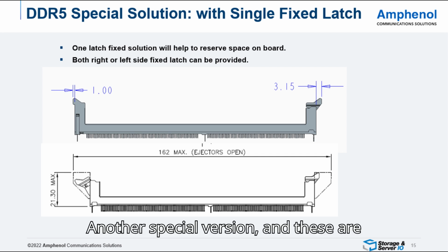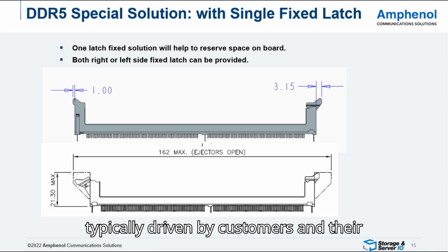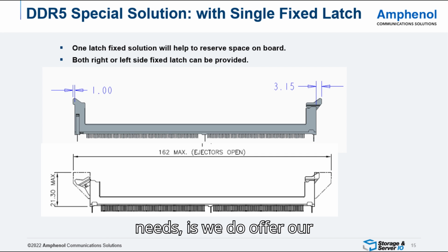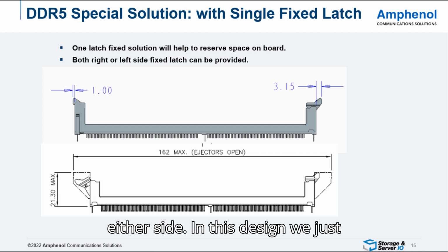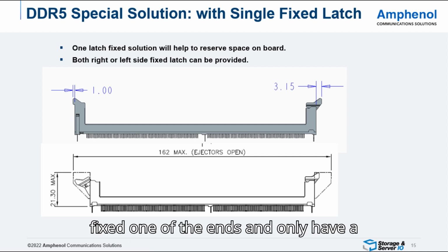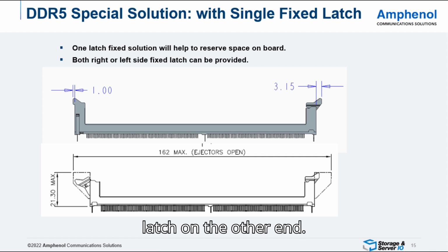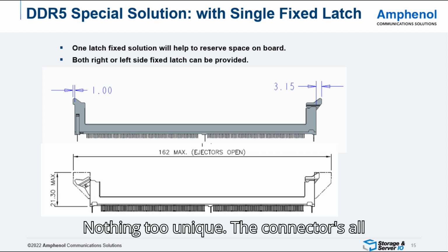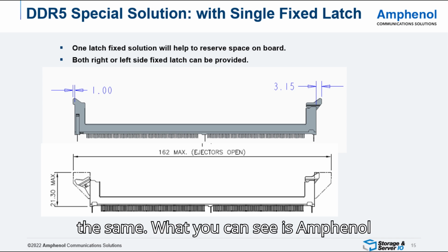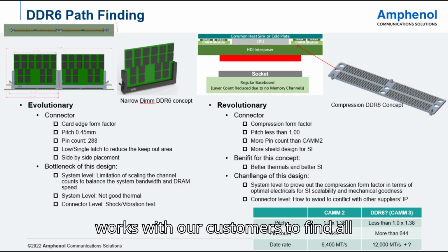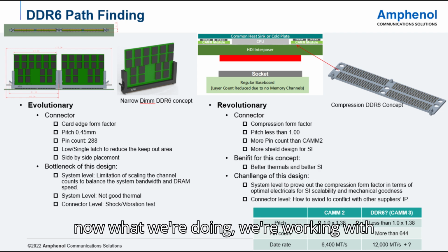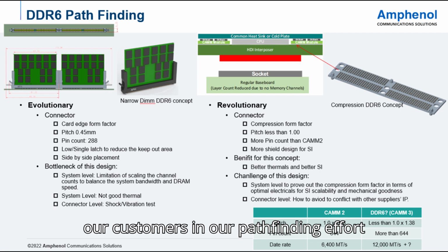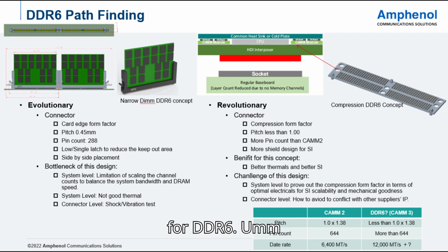Another special version, and these are typically driven by customers and their needs, is we do offer our DDR in a single latch solution, meaning typically the DDR has latches on either side. In this design, we've just fixed one of the ends and only have a latch on the other end. Nothing too unique. The connector's all the same. What you can see is Amphenol works with our customers to provide all these different applications. And right now, we're working with our customers in our pathfinding effort for our DDR6.